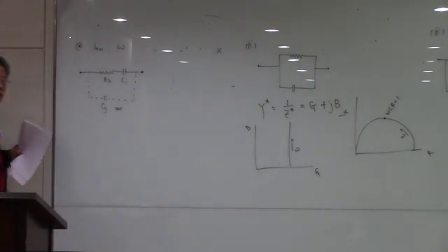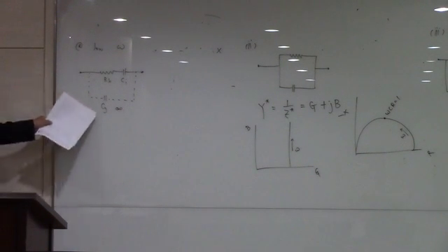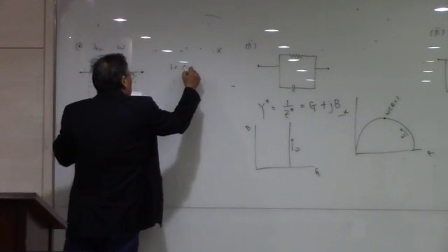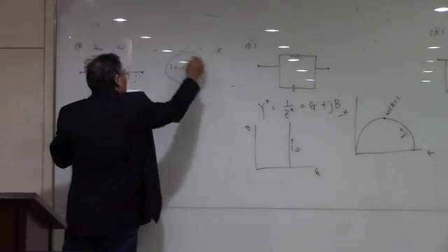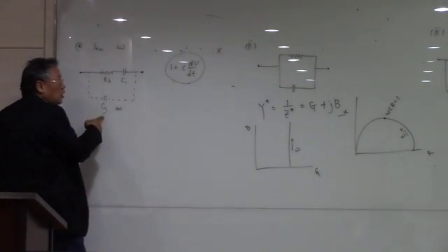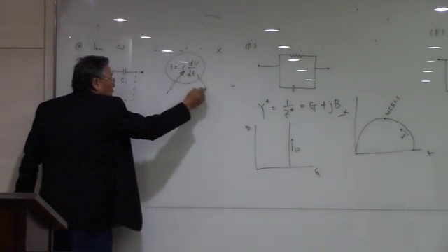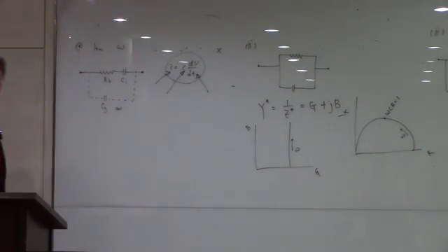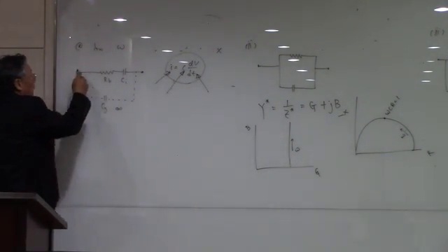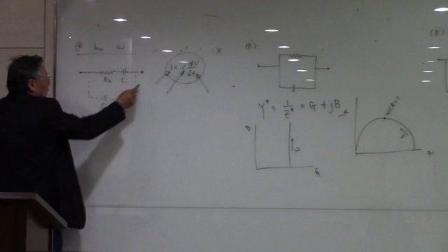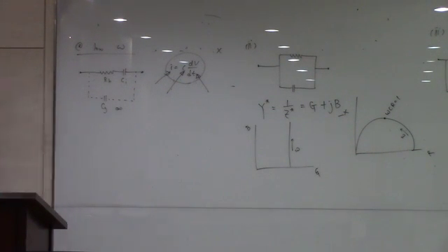The impedance is infinity at the low frequencies, because the current that we're going to have is going to be, see, C dV over dt. And in this Cg, this is low and the frequency is low, so the total current is almost none. Okay? So at low frequencies, the whole circuit is going to be simulated as the series connection of capacitance and the resistance.